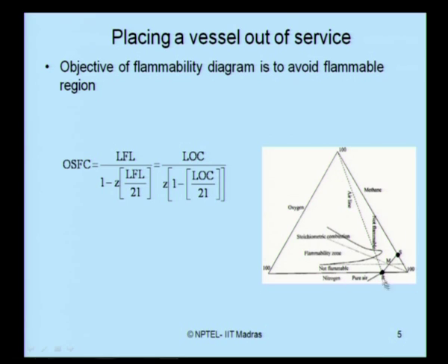The air line is the line which joins the apex to the nitrogen concentration of about 79% in pure air. So, I draw this line and then I get the stoichiometric line for a stoichiometric condition given for a specific mixture. From the stoichiometric concentration reaction I get this line, then I mark the LFL and UFL of the mixture on the oxygen arm, then I keep on drawing the nose of this curve, and this becomes my flammable region, which is already known to me.